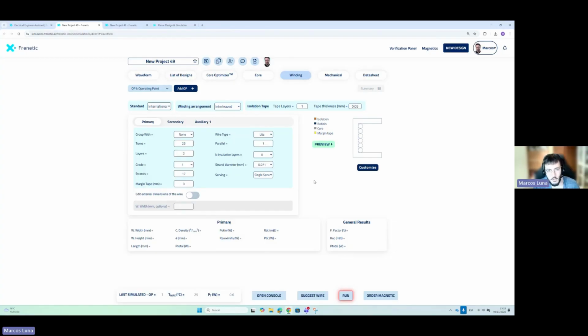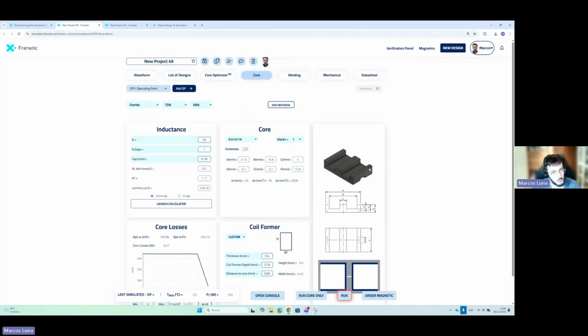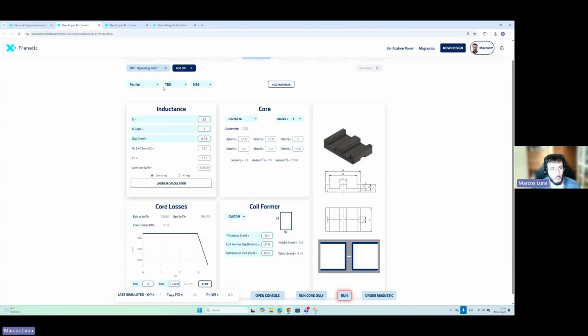No, you can do it. You can pick the wires and you can try different options, okay? But at least at the beginning, this shape is not suitable for allocating a winding inside. So we can use the planar and create a planar or a PCB winding to allocate the winding, and also we can use this to integrate it in our PCB.